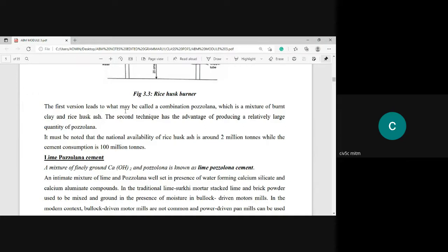Okay, so what I started to think was that I need to search for an alternative pozzolanic material that is locally available and more predominant. In that context, in 2011 or 2012, I started my research with a material called bagasse ash. This is a material you are going to obtain predominantly in the southern part of Karnataka.